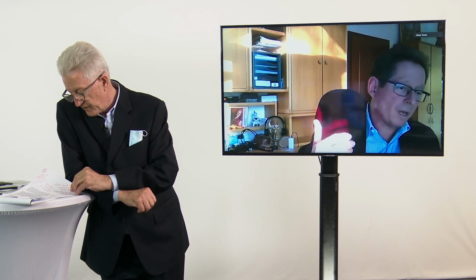My last question to you, Thomas. Can we also save energy with such a system? In future, maybe we can measure the current, we can measure the torque and so on, and maybe we can check this and look at the projection of the motor, and maybe the motor is too big for this application, and then we can offer a smaller one, and the customer can exchange it.